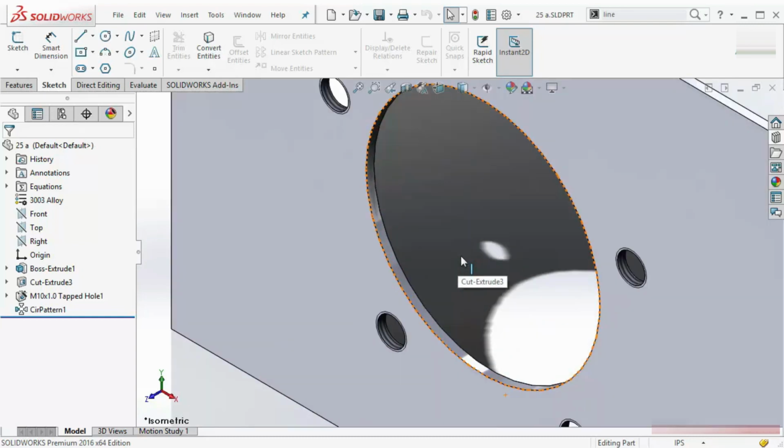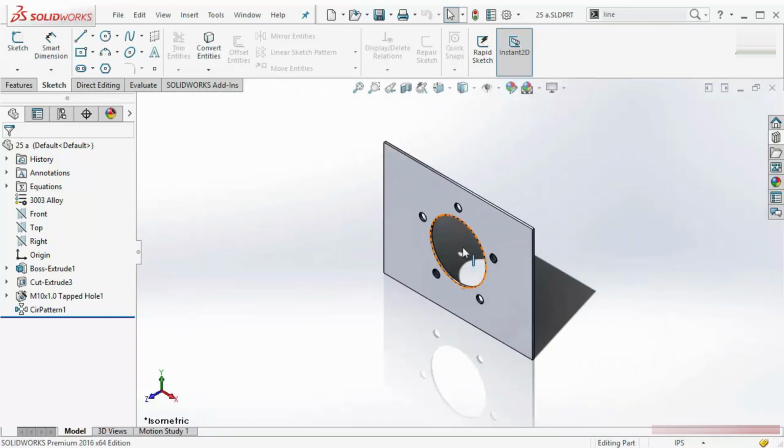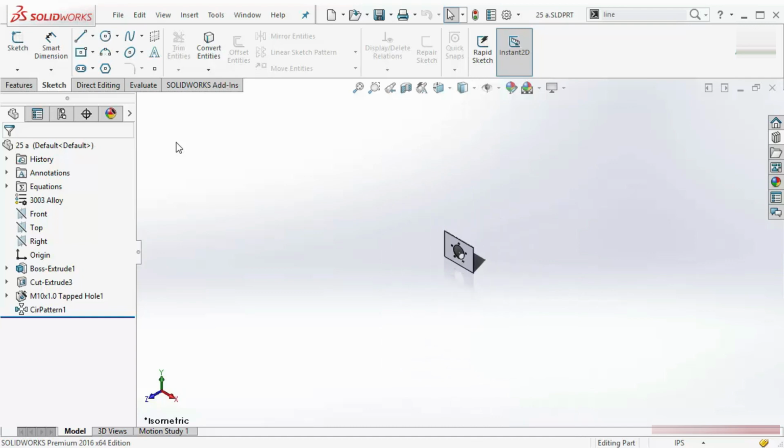So this is how you can zoom in or zoom out, but your mouse cursor position is very important. Let's say my mouse cursor position is here. Now if I zoom out, you will see this is going away. That's fine. But now if I zoom in, if I scroll up, you will see this model will go away from this window.